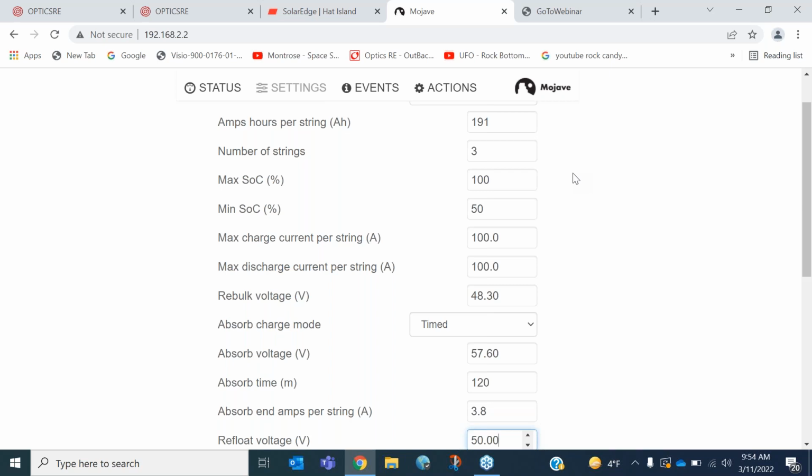Good question. I'm not 100% certain on that, because you are AC coupled. If you're on the grid, yes. If you're off grid and AC coupled, I would have to say probably no, because we're going to stop inverting at low battery cutout.